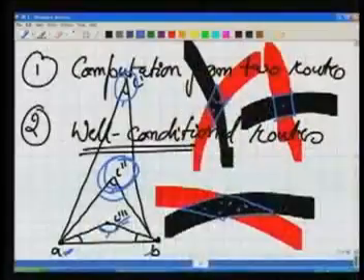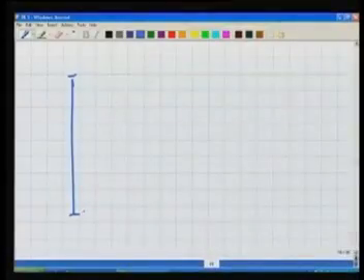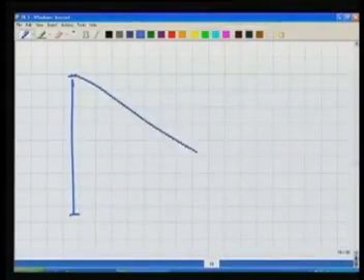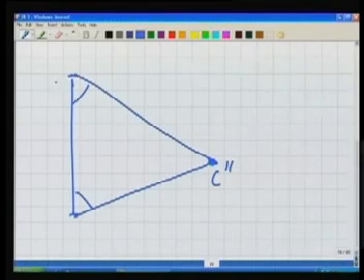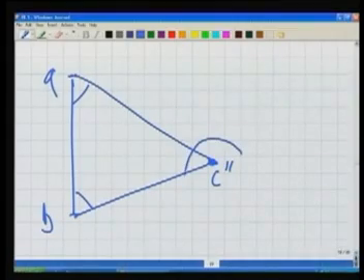The same thing we do in the triangulation. Though we do the computation from a known length, the base length, from the known angles, we measure these angles, we are trying to fix this point C double dash from this A and B. Now, depending how much uncertainty is there, it will depend upon the kinds of the angles which are there in the figure.